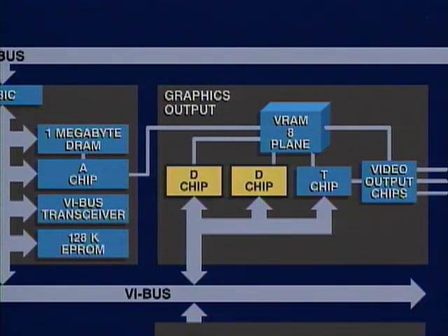The data chips process pixel data during hardware-assisted operations and provide the data path between the buffered VI bus and 4 planes of display memory. The graphics subsystem architecture supports up to 7 data chips for a maximum of 28 planes. But the VAXstation 3520-3540 uses a maximum of 6 data chips or 24 planes.